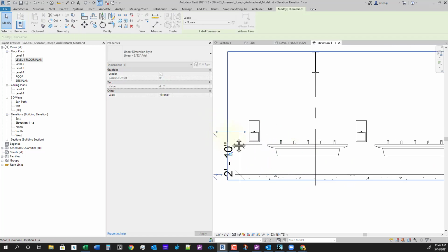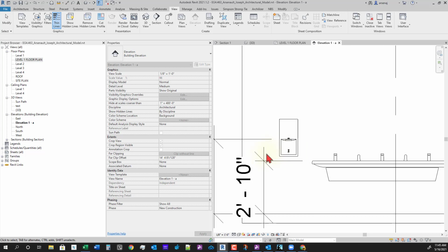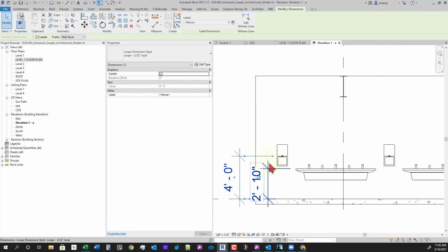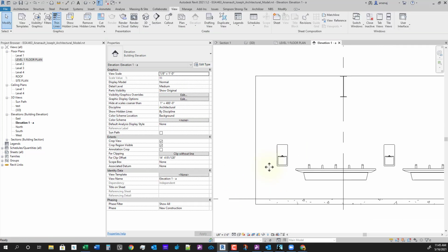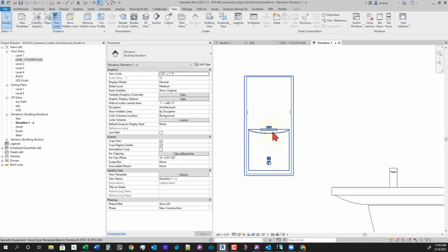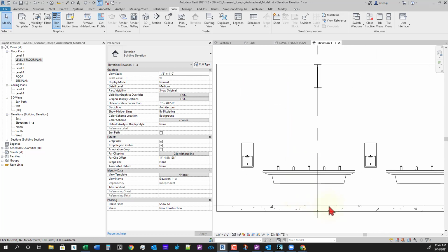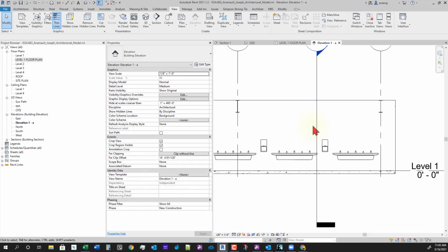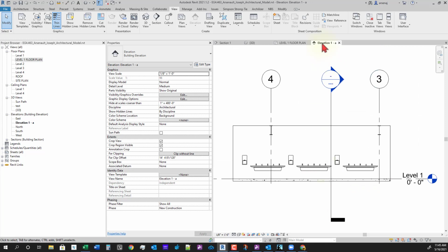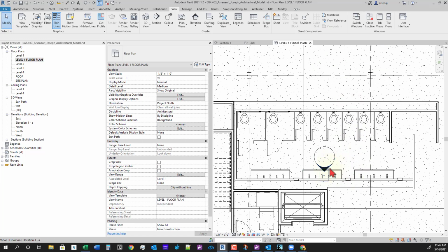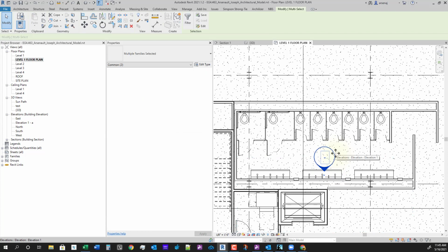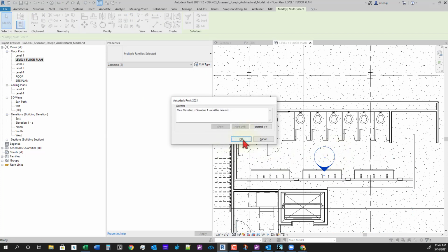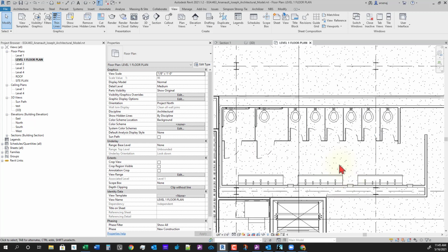And then I believe that brick was 4 feet to the bottom of this hand thing. So it looks good. I'm going to kill this elevation. I just wanted to check that. Hit OK to delete it. I selected both the elevation bubble and the arrow to delete it, or you could have come over here and just hit delete.